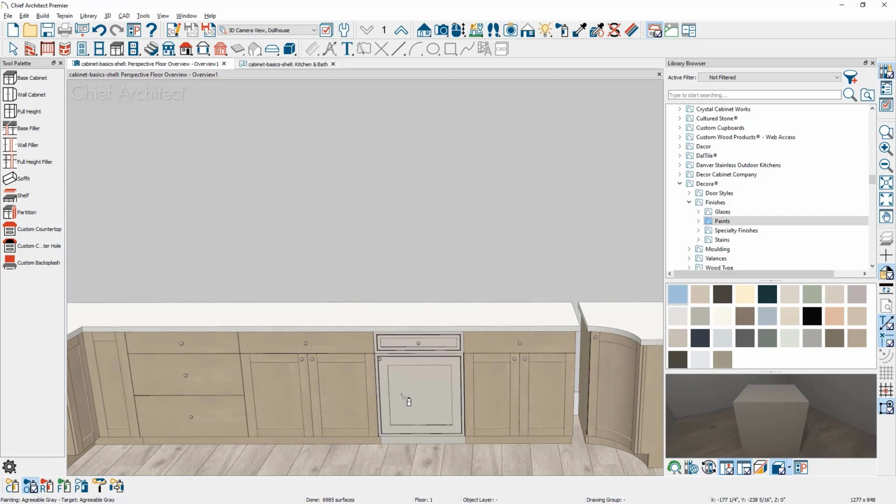Now you're going to notice a few tools down in my lower edit menu. These are scoping modes for applying the wood species or the paint. These stand for component mode. If I'm in component mode and I only click on a portion of the cabinet, it will go down to the component. The object mode is the entire box, and then there is a room, a floor, and an entire plan that will replace those materials depending on the scoping you have set for the Material Painter.